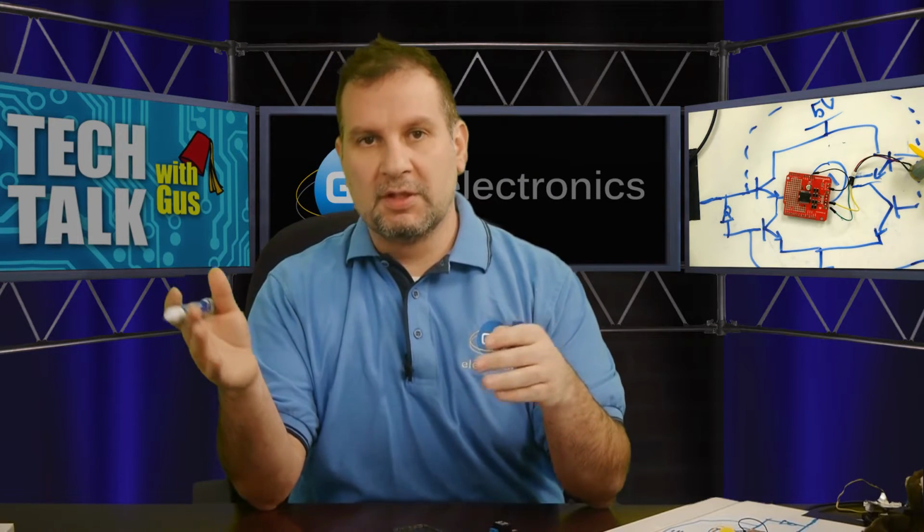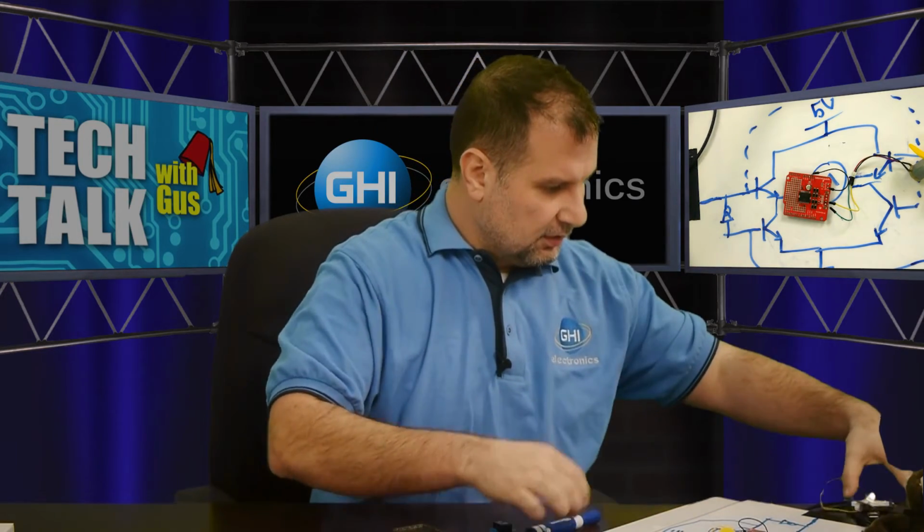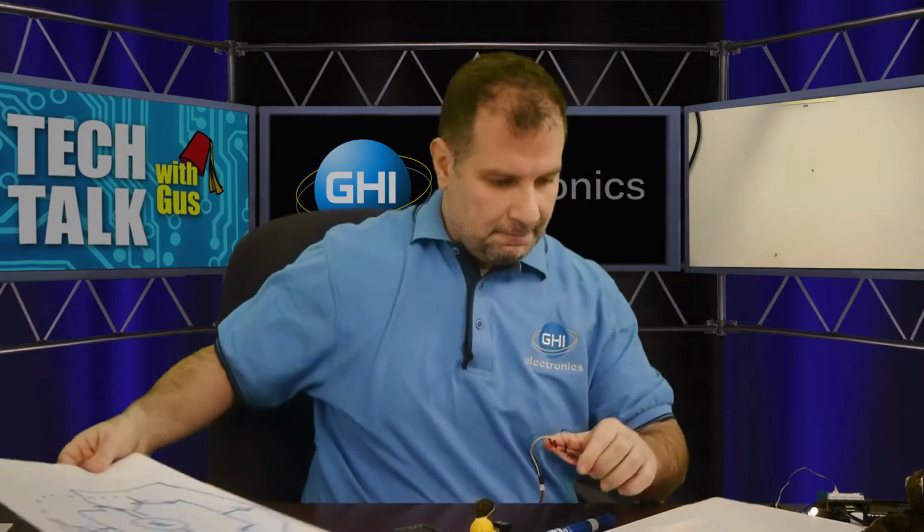You would have a direction pin, and then there's a PWM pin. The PWM pin is what you would use to control the speed of your motor, and the direction pin is to control the direction of the motor. And I actually have a little demo on this here.